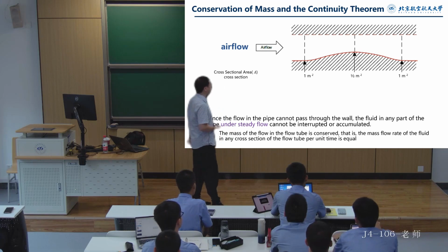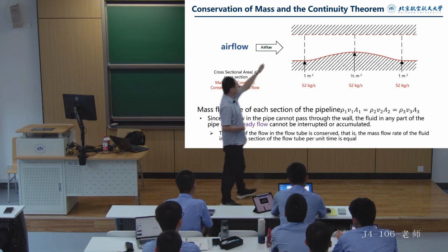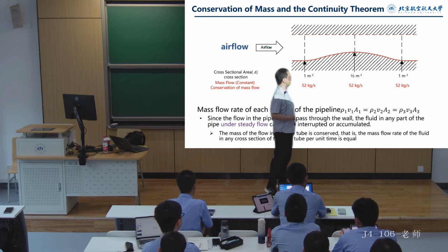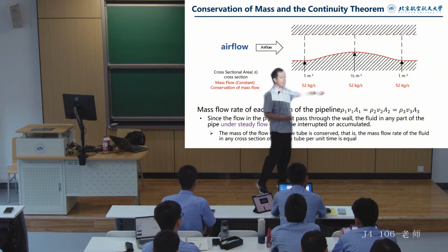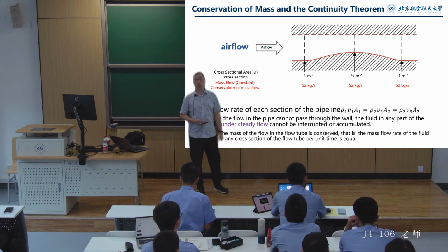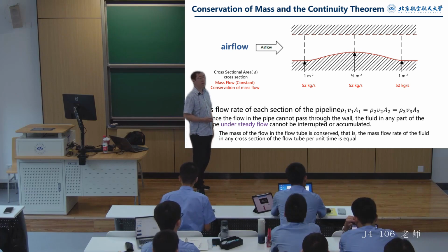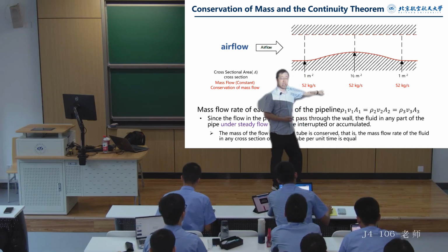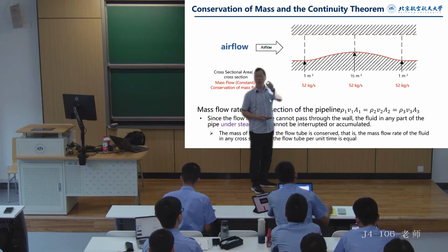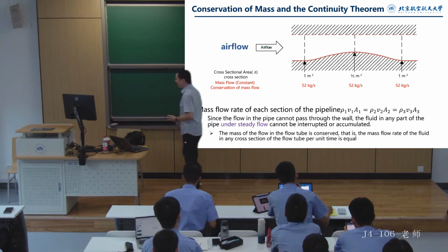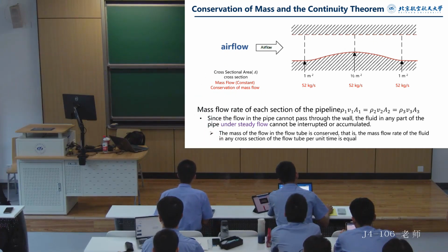With this relationship established, we can understand that for each cross-section, we can formulate an equation. At each cross-section, the cross-sectional area A multiplied by the corresponding velocity V, and then by its density ρ should be calculated. The product of these three should be a constant value, which means the mass flow rate remains unchanged. Now, why so? Why do we use V here? We can assume a very short period of time, such a brief moment. And during this short moment, the distance traveled is very short. At this time, in fact, the cross-sectional area hasn't had the chance to change.